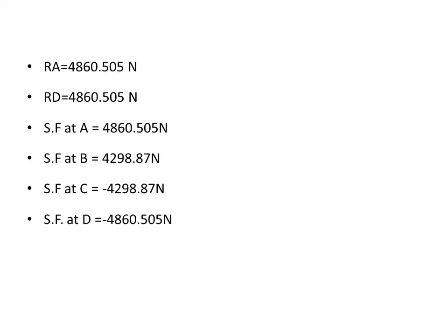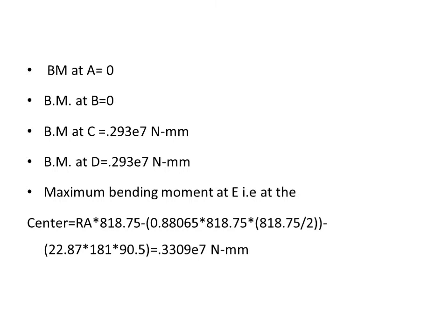This is the bending moment calculation of the shaft. The maximum bending moment at the center, RA into 818.75, is equal to 33097 Newton millimeter.